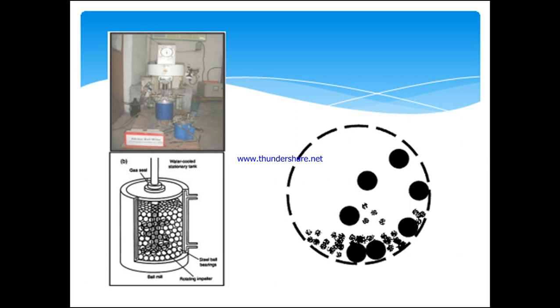And in this ball milling process, the selection of the ball material influences the type of material obtained, that is, the harder material balls for synthesis of the softer material. Alpha alumina and zirconia are widely used ball materials, as well as tungsten carbide or high speed steel. Based on the material, that is the grinding ratio, or the size of the particle which we want, we are going to use different types of balls here. So what are the advantages of this ball milling?